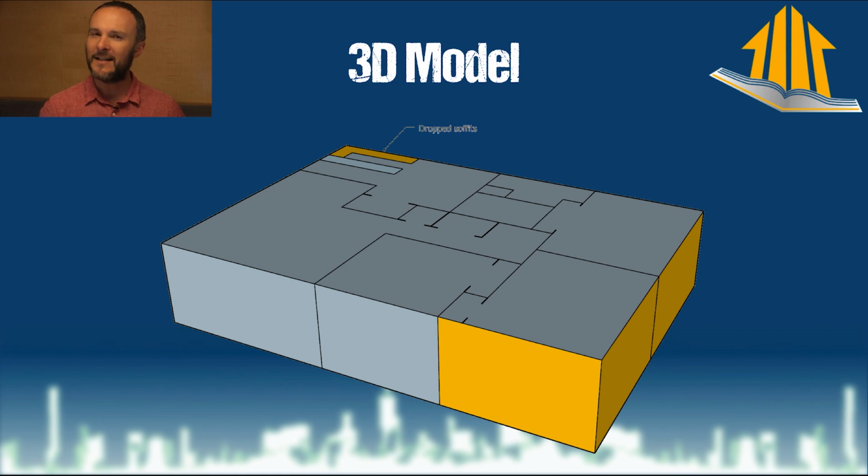That is not going to tell you the whole story, because at that point what you need to do is take this report and build a duct design out of it and install actual ducts and registers, and you're just guessing. If you just say, okay, well that room is bigger than that room, therefore I should give it, let's say, 20% more heating and cooling than the other room, but I'm not paying attention to my window placement, which way is west, and all that stuff, you could definitely screw that up. What's better is a room by room load, and that is what we're doing here.